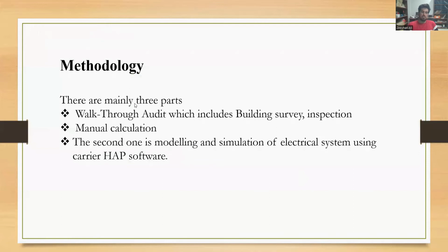Methodology. There are mainly three parts of our work. First of all, we did a walkthrough audit, which includes building survey, inspection, and manual calculation. And then we worked on modeling and simulation of the HVAC system using Carrier HAP software. We also worked on lighting load elimination using a lux meter.